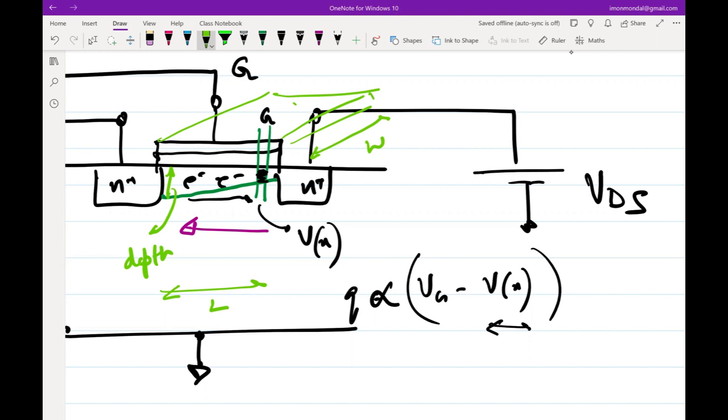Okay. So as it turns out, for a circuit designer, the things that are in your control are these lateral dimensions, W and L, which you can vary. You cannot vary the thickness of the oxide, Tox, as a circuit designer. You cannot vary the doping.